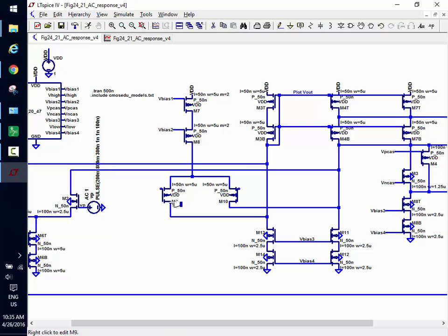This one will pull 10, but there's 0 current left to pull through here, right? So I look at the water flow. Got 20 flowing through here, 10 through there, 10 through there. If I bias this with these sizes, then the 10 goes through there and the 10 goes through there. There's nothing left to flow up here and these shut off. Does everybody follow that? So they just kind of swap.